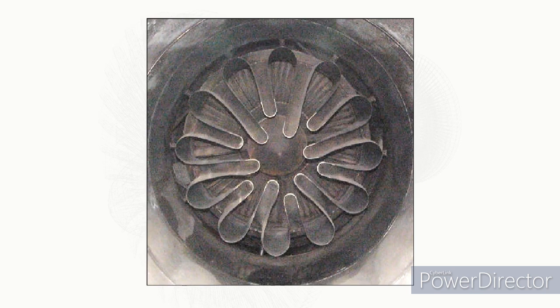Whereas the modern gas turbine engines could take advantage of the new methods of sound-absorbing materials, aircraft fitted with older, pure turbojets had to find some other system of reducing their noise output. Aircraft can still be seen with corrugated internal mixers and lobe-type nozzles fitted to the rear of their power units. The latter cause the gases to flow in separate exhaust jets that rapidly mix with slower-moving air which is trapped by the lobes.